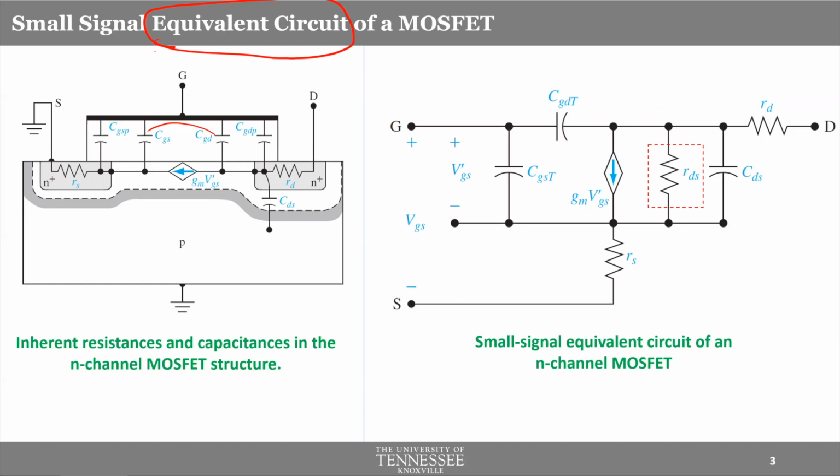We mimic the high level behavior of a novel device, which is usually very complicated, using these basic circuit components, so that we can simulate it using basic circuit simulators. That's the ultimate goal. To do that, we have to break down the overall structure of a MOSFET into smaller components and represent different aspects of it with different capacitors, resistors, or other circuit components.